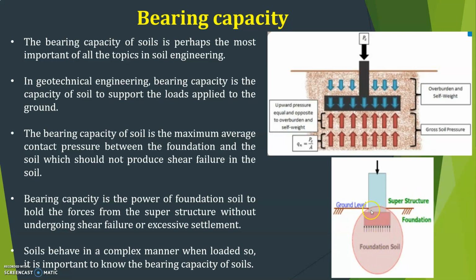You can see here, this is the superstructure, ground level, and this is the foundation level. Okay, so this is the foundation and foundation soil. And here, there is a load from the superstructure because of overburden and self-weight. So, the soil exerts pressure in the upward direction, opposite to the overburden and self-weight.